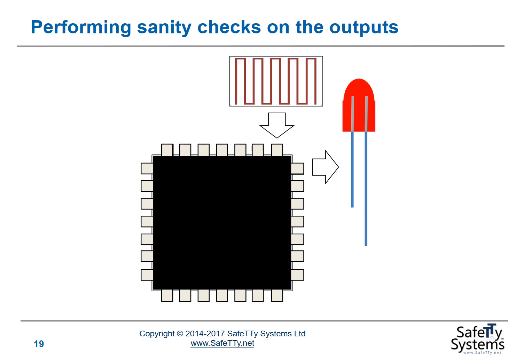Very simple example. Suppose we've got a heartbeat LED function. This is our heartbeat LED. We've talked about various configuration checks that we've carried out to make sure the registers are correct, to make sure the static variables are correct. We could consider adding some form of light-dependent resistor or some other form of light sensor to confirm that our heartbeat LED was operating as we expected. In most designs, this would be overkill. This would be more than would be sensible or necessary to meet the needs of the application.